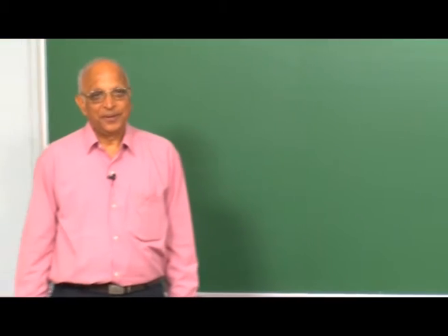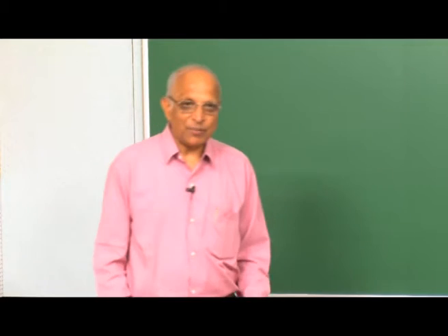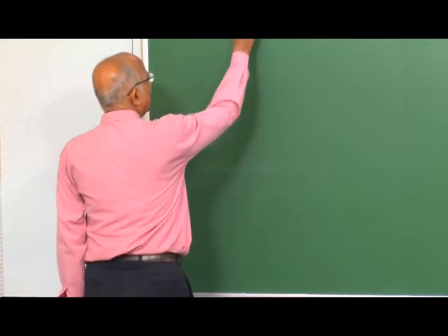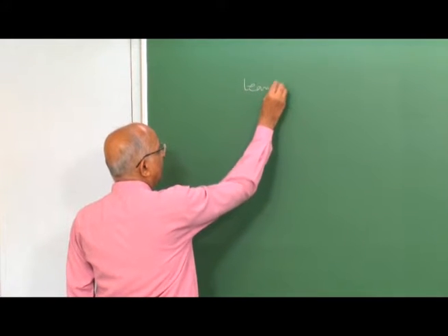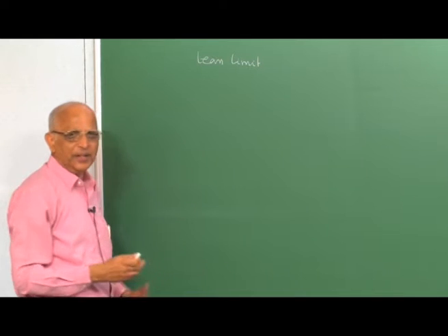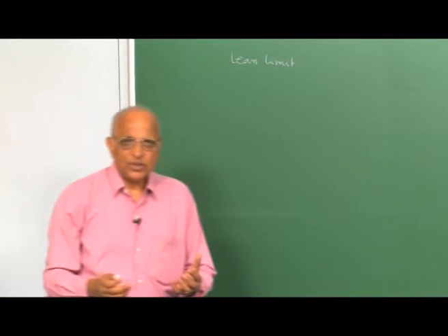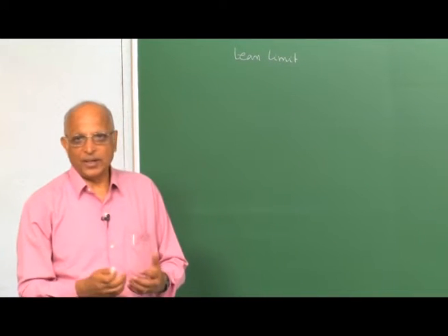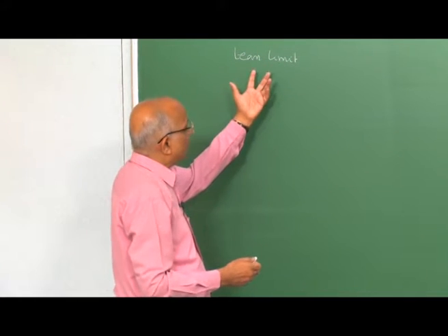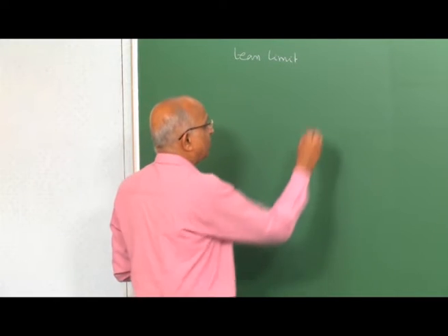Good morning. In the last class we discussed the limits of flammability, especially the lean limit of flammability. The lean limit is an important safety criterion in that if we have a spill, let us say, of a volatile liquid and the vapor comes out of it, and if it is able to form a mixture within the flammable limits, what did we tell?